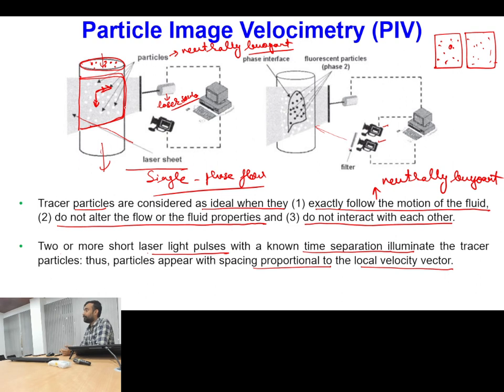Okay, and now if you have to see the third component of the velocity, then you have to eliminate it in the other direction. So you have to make your laser sheet in this plane. And there are techniques which are called time resolved PIV or high speed PIV measurement systems. What these time resolved PIV can do is, you can keep on swapping the planes in the depth direction and measure the velocity at multiple planes in a very small fraction of time. That all depends upon your system capabilities. Okay, is that point clear?